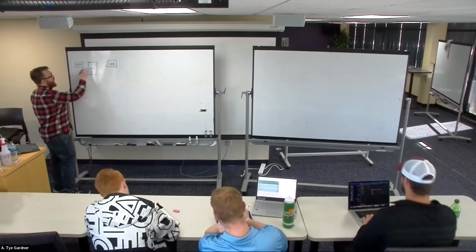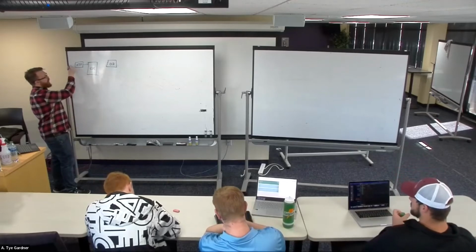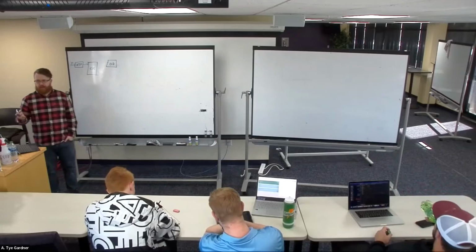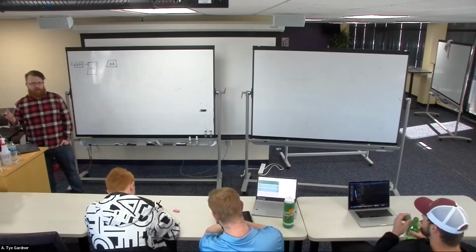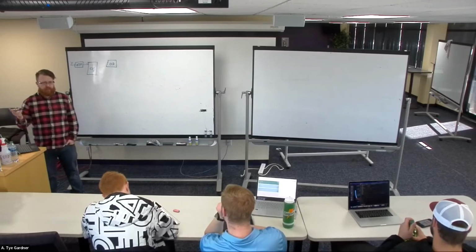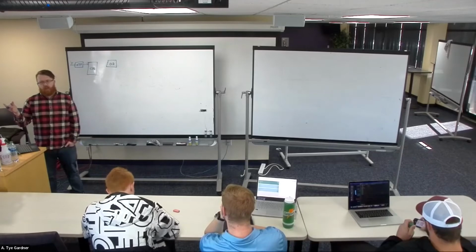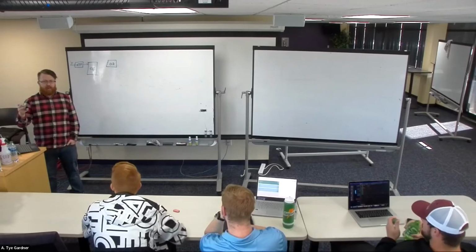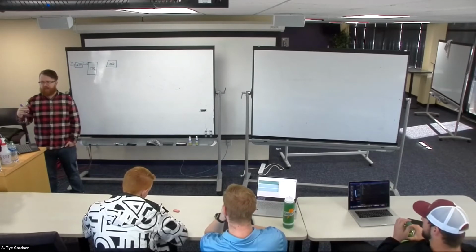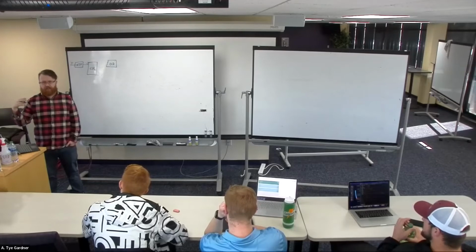And so the next state decoder is combinational logic that looks at whatever the inputs are, and this could be a range of an input, right? So in the case of the garage door opener or a garage door in general, there are 2 inputs to your state machine, essentially, from the outside world perspective, which is the button that you push and the little sensor that you would walk over and it would not hit you in the head, right? That auto detect. There's really 2 inputs. And then there's the current state.